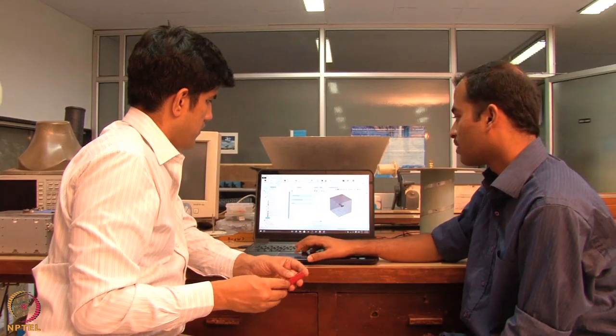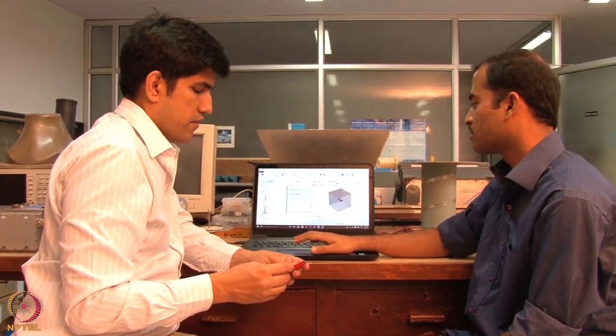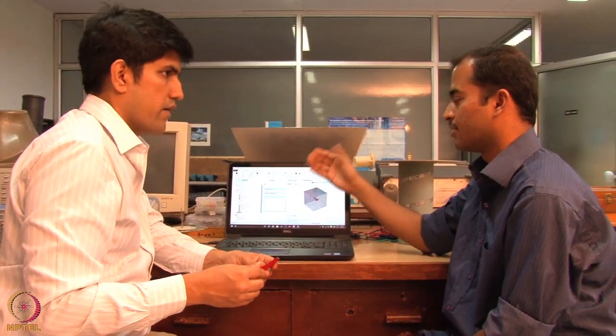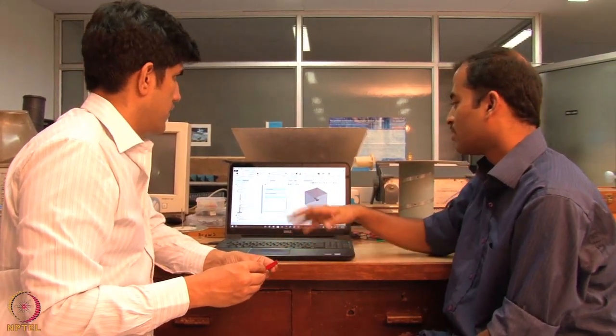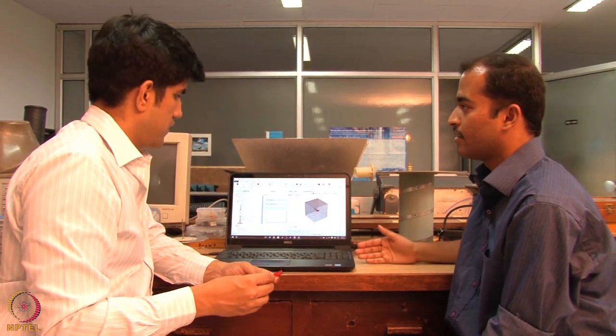What this solver gives is inbuilt physics-controlled meshing. It gives different options of finer and finer meshing. The thumb rule is that, experimentally or iteratively, we can go finer and finer till the results of two settings come the same, and then take the larger setting. That's the convergence aspect you're looking at.